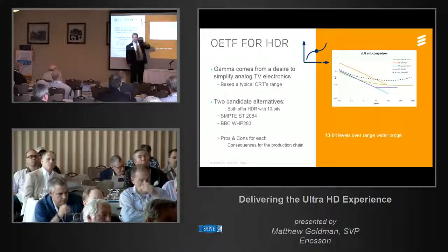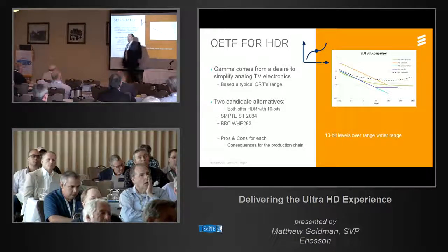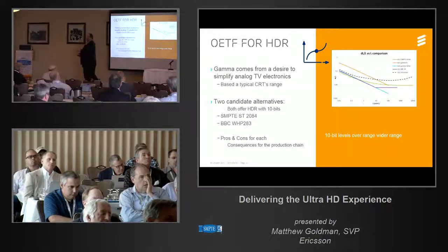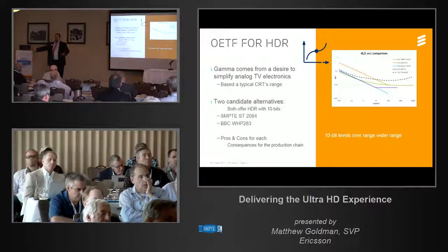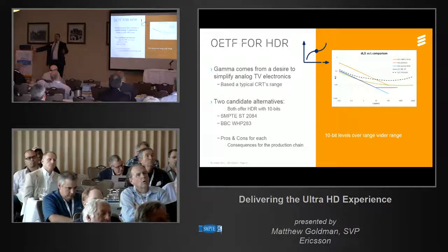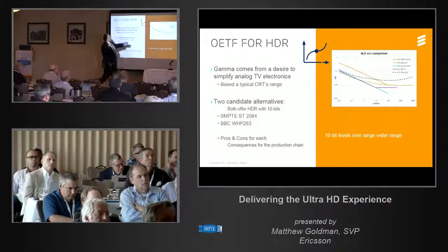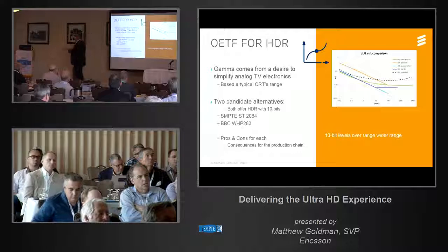The reason they're doing it their way is because when you slide this curve forward, the blue one, they figured out that at about 2,500 nits, which is a pretty decent compromise for a high dynamic range versus going hugely up to like 10,000 nits, they can do the same curve for your standard dynamic range television as for your high dynamic range one, so it's backwards compatible. When the material gets really bright, that's when this curve comes into play, but your standard dynamic range TV can't display it anyway. There's a backwards compatible thing.